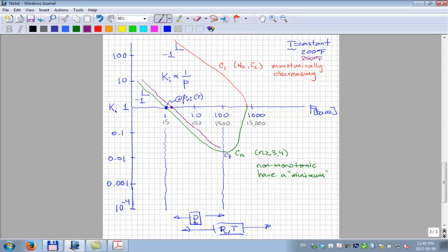So in this low pressure range, we have a relatively easy problem of coming up with the K values. For all these different components, all we need to know are their vapor pressure curves. People way back were correlating vapor pressure curves of all these components, pretty much everything we'll ever see, with very simple relationships. If we know a little bit about each component, either its name or something about it, we can generally come up with the vapor pressure curve. Once you've got that, you've nailed all the K values in this low pressure range.